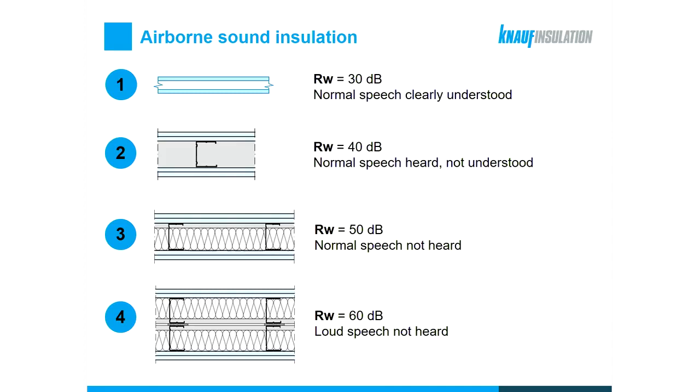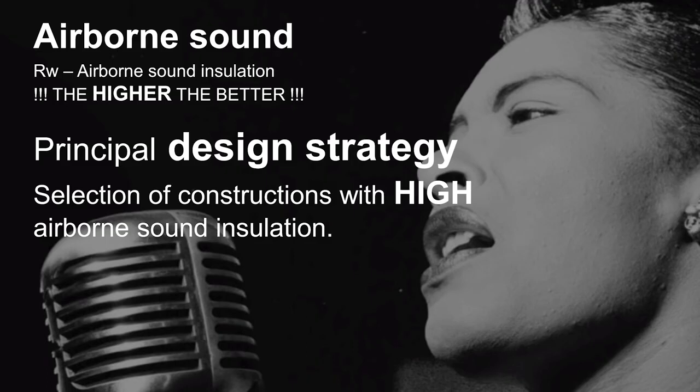So you can see that there are very, very fine limits between these ratings, and all these are actually subjective. So it's not easy to make everyone happy all the time, and this is exactly the part of the story on the difference between the acoustic regulations, which maybe stand around the level of 50 decibels, and the acoustic classes, which could go even above 60 if we decide to build a project worthy of a luxurious acoustic class.